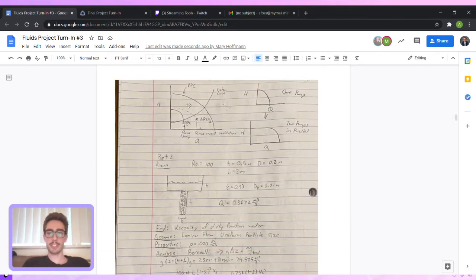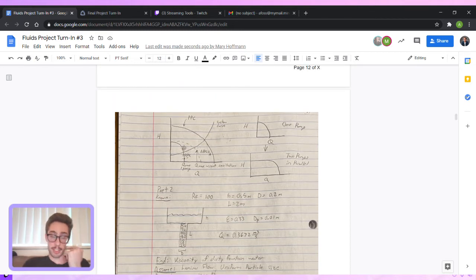The next part of the question asks us to draw a pump diagram for this system. Basically, there's a pump performance curve and a system curve, as well as net positive suction head required and available. And these are displayed on our graph right here. When you go from one pump to two pumps in parallel, the flow rates are actually additive, and so the curve will extend to double the length in the Q axis.